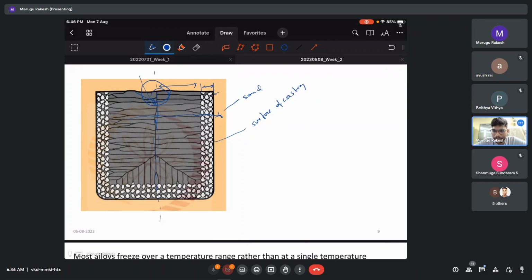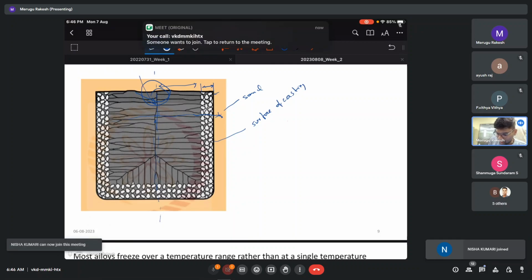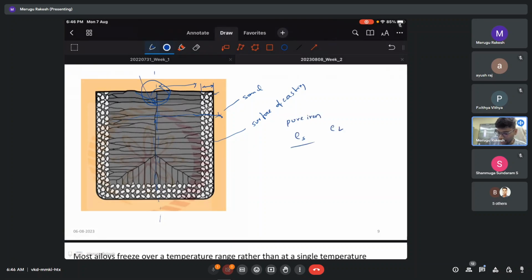So there was a question. Yes, the solidification volume shrinkage occurs. Here also the volume shrinkage occurs. Whenever you are free, just search this on the internet. Take pure iron, take the density of the solid, take the density of the liquid, and check whether they are equal. Take pure iron, pure aluminum, pure magnesium, all pure metals, then see their density in solid as well as liquid. You'll see the difference. If there is any difference in the density, there will be shrinkage happening. And of course shrinkage happens in pure metals as well. Correct me if I'm wrong.